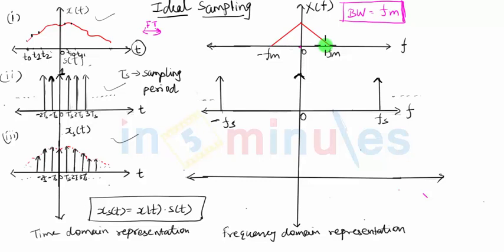The next thing we want to do is write down the frequency spectrum of the sampling signal s of t. S of t was a time domain signal. Now we get S of f, which is a frequency domain signal. If you observe carefully, we have shown three impulses in the frequency domain representation. But these are not just three impulses. As you can see, I've put the dots. That means there are multiple impulses all occurring at a specific gap.